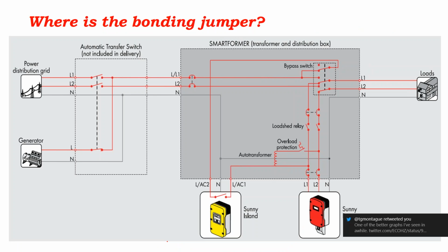That's why we use solar racking systems, and that's really the difference between a metal roof and a homemade racking system versus using a solar manufactured racking system. If you're homemaking your racking system, you still have to use a listed grounding method. And if your metal rail is not listed as a ground path, instead of grounding the modules to the rail, you have to ground the modules to each other, and you still have to ground the rail, but it's not listed as a ground path from the modules through the rail to the grounding system.